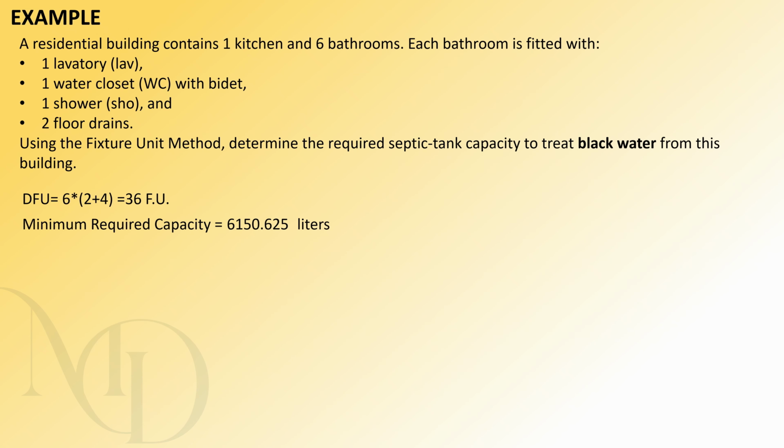The computed capacity is 6,150.625 liters, and this will serve as the minimum required capacity. This value also represents the total liquid capacity of the septic tank, written as V sub LC. To convert it into cubic meters, we divide the liters by 1,000.